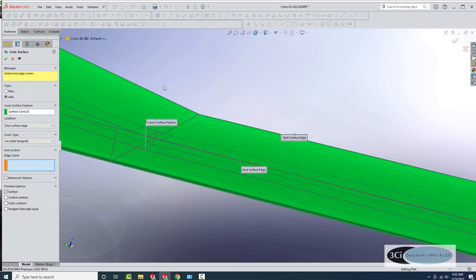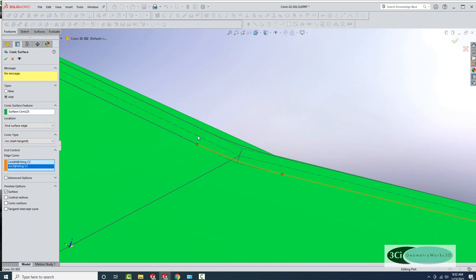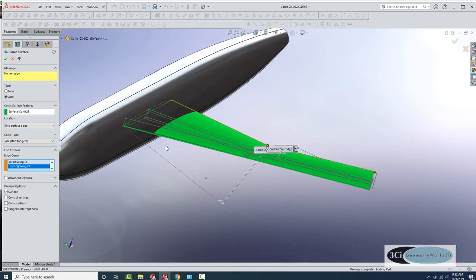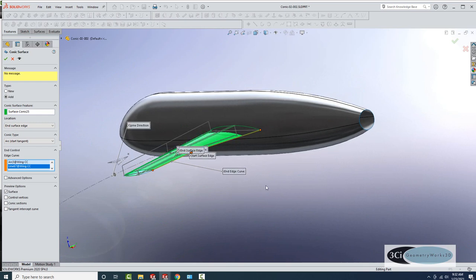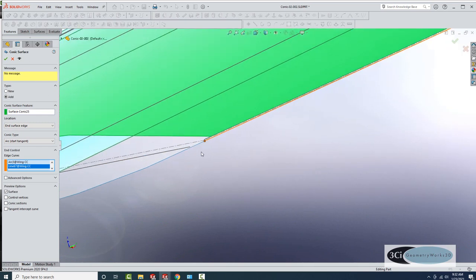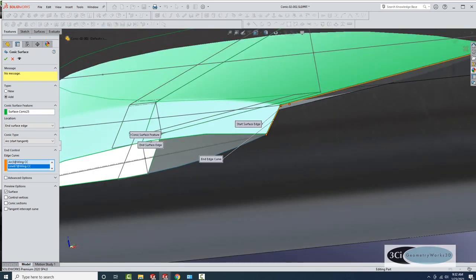So it inherits a slope from the previous bay. All we need to do is select the aft or trailing edge curves. And this creates a loft wing type surface. Very simple, but at least it accounts for all of the elements required to define a wing.